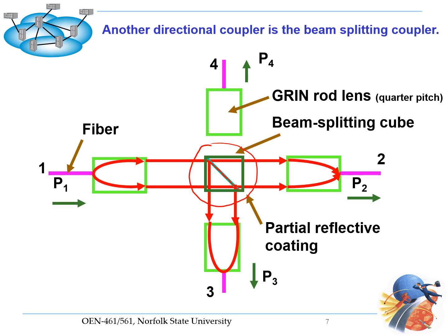And let's say we have 4 fibers, labeled 1 through 4. Attached to each fiber is a lens. It could be a graded index lens as depicted here, or a simple aspheric lens collimating the light. So light emitted from the fiber will be collimated and continue to the beam splitter.